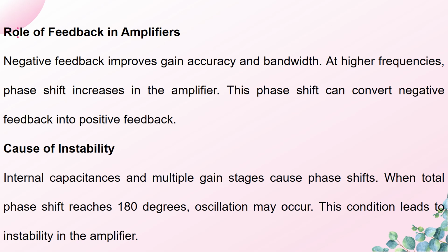So next let's see the role of feedback in amplifiers. Negative feedback actually improves the gain accuracy and also the bandwidth. At higher frequencies, phase shift increases in the amplifier. This phase shift can convert negative feedback into positive feedback.